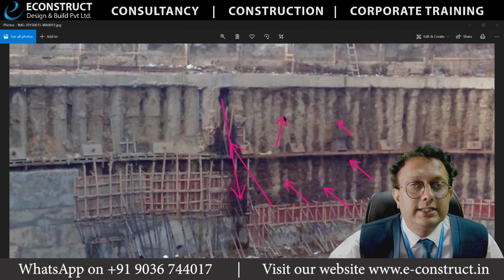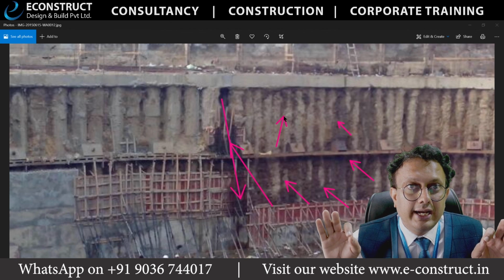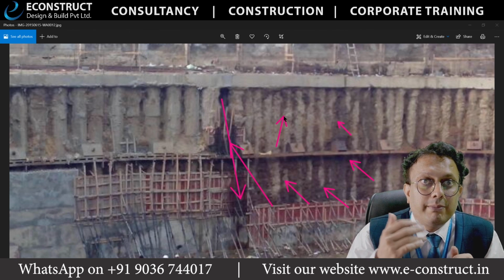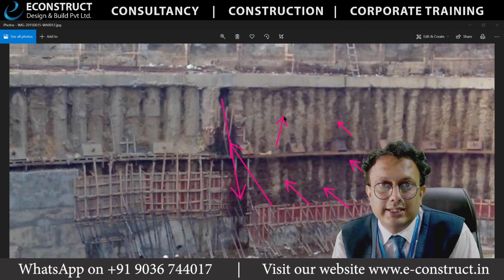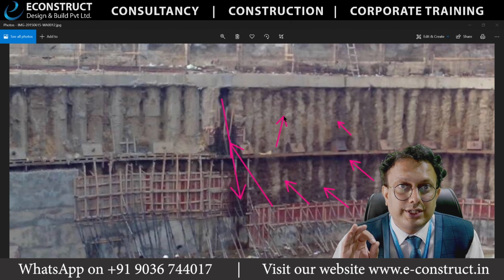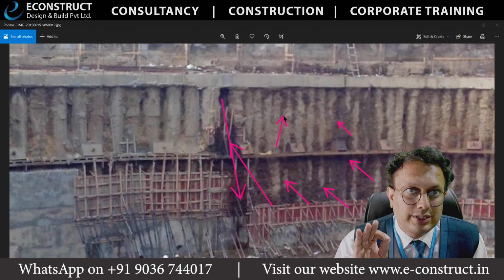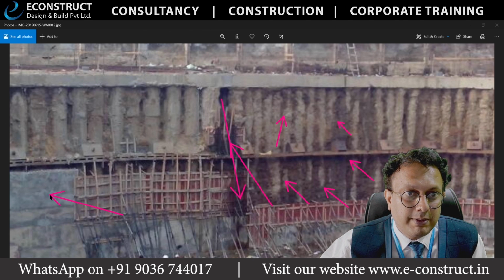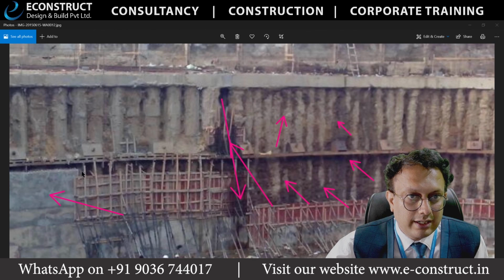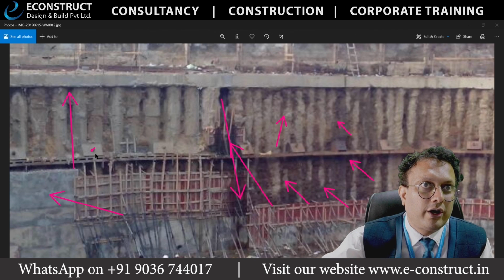So this comes under the temporary structural analysis, design and execution. This doesn't come under the permanent execution. Please understand that very well. Come on, say it behind me. This is temporary structure. Shoring piles, shoring beams and all, everything is temporary structure. Whereas the retaining wall, the permanent structure starts with the retaining wall. The moment the retaining wall comes here and goes up to here, at that time this will be removed. Why? Because the PT strands are going into the neighboring plot.